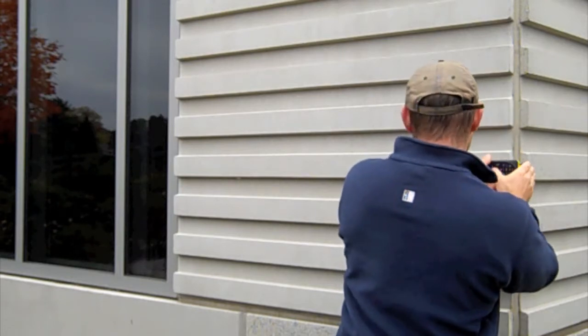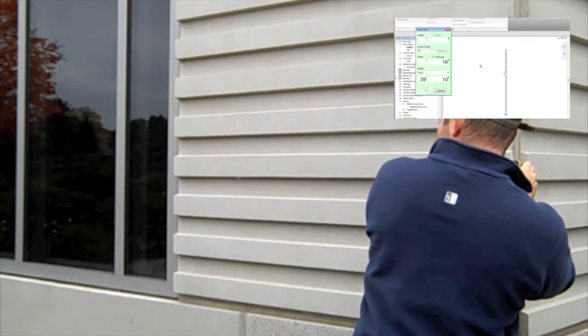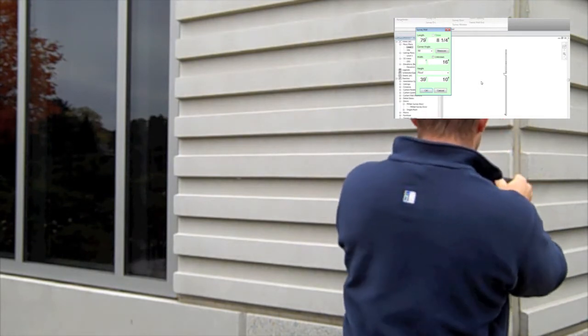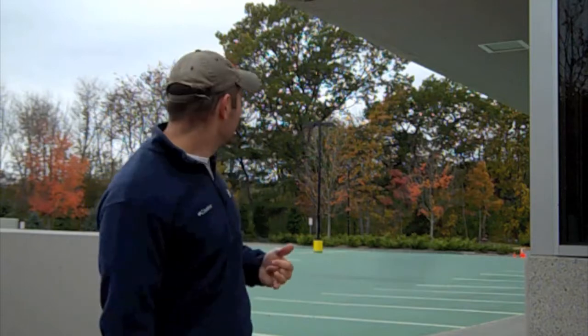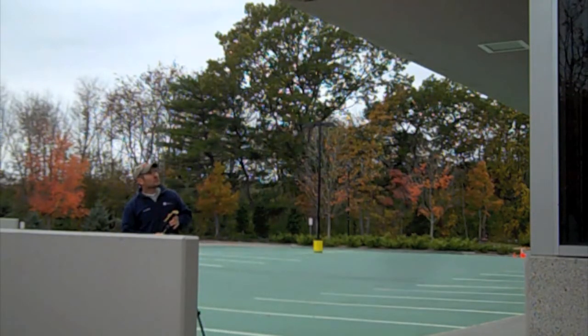In this instance, I'm going to go counterclockwise, measure the distance, put that in. Now we need to determine the length of this projection from the facade of the building. Now, if you're taller than me, you might be able to reach up and measure back. But in this case, I need to use some of the onboard functionality of the Disto to determine the length of that projection. And I'll do that next. Projection. Along to this point. That projection is 6 feet long. And we'll enter that into the model.